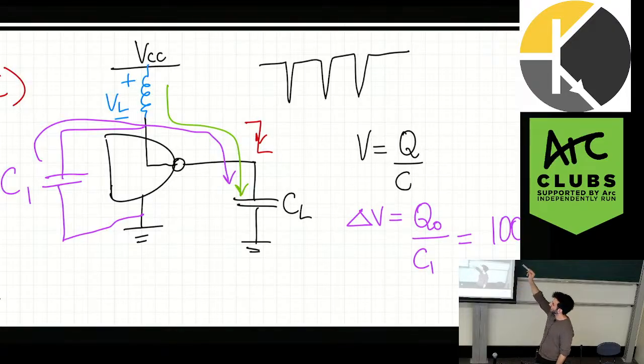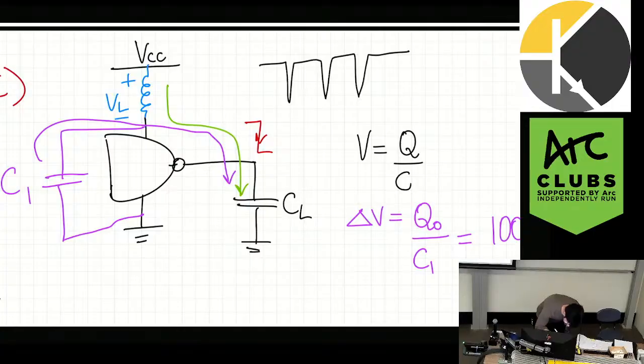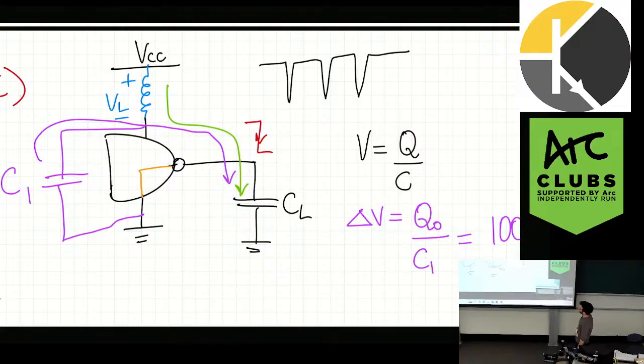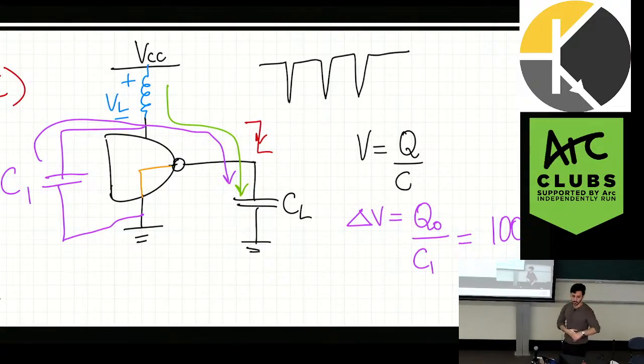So it was pulled to high for VCC, but then a high to low transition happens. How does it become low? Ground. That's it, right? So we no longer have this anymore, and we are now pulled to ground. All right. Now, the resistance in the NAND gate might not be the same as RU1 anymore. Yes. So it might no longer completely absorb. Yeah, that's true.